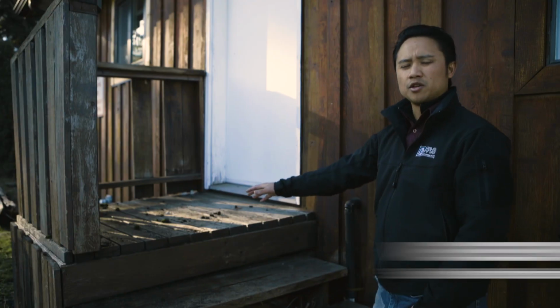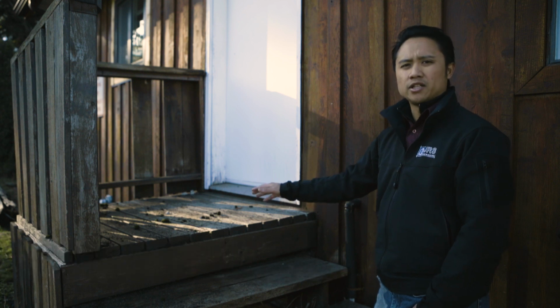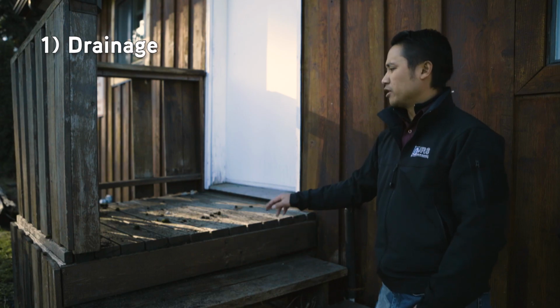Whenever looking at balconies, you want to remember the 4 Ds in building envelope design. The first one is drainage. You want to make sure that water is able to drain off the balcony either through the slats or off the balcony itself. Number 2 is drying.